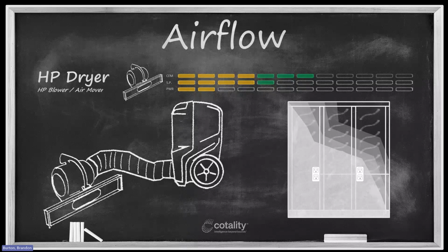The first step would be to remove the base trim from the assembly and then give myself an access point at the base of this cavity. That access point doesn't need to be any bigger than what will be covered up by the base trim when I put it back in place.